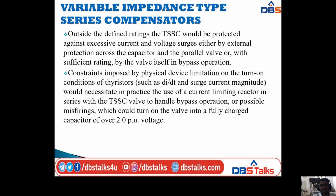Outside the defined ratings, the TSSC would be protected against excessive current and voltage surges either by external protection across the capacitor and the parallel valve, or with sufficient rating by the valve itself in bypass operation. So outside the defined ratings of the TSSC, we are taking protection against excessive current and voltage surges.